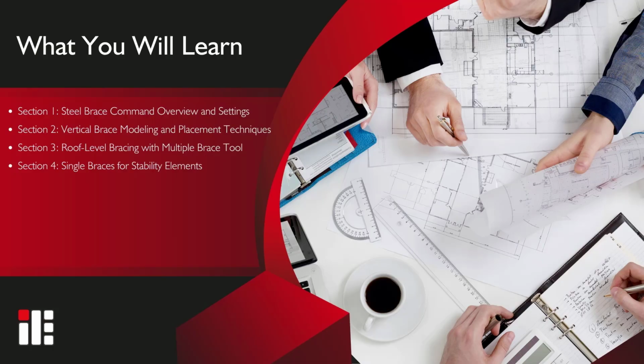This tutorial introduces steel bracing tools in ideCAD Structural. It covers vertical brace modeling between beams and columns, roof-level bracing using the multiple brace tool, and the placement of individual braces for localized stability. Settings such as section selection, connection types, alignment, and effective length definitions are also explained. By the end, a complete bracing system can be modeled for wind and seismic resistance.